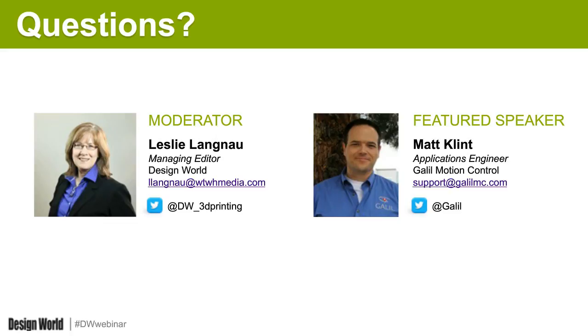If you need to control servo motors and I/O or steppers across a large physical range, and I keep using the example of a factory floor because it's really where it shines, then EtherCAT is really something you need to look at. Ethernet communication would be specifically between an HMI or a PC and a motion controller, which is handling the real-time motion. So it really is a question of the application for which one is better.